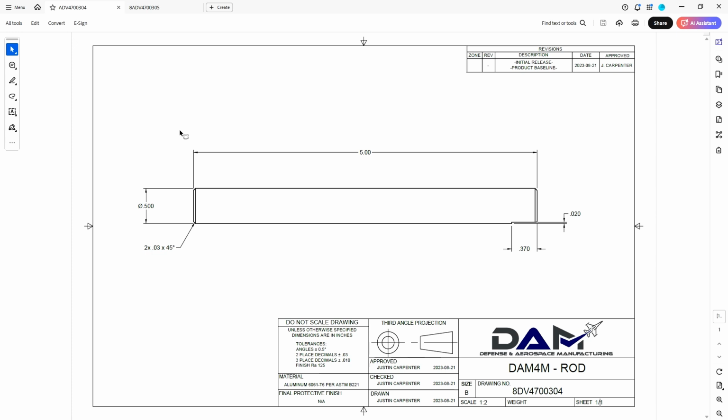And the reason I'm going to revolve this is it's cylindrical. It could be developed in a different way, but if you suspect the part may be turned or goes on a lathe, or is going to be spinning around a rotary axis, it's likely that having that center axis could be setting up your model in a way that's conducive to that CAM process.